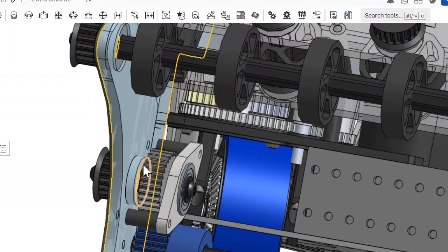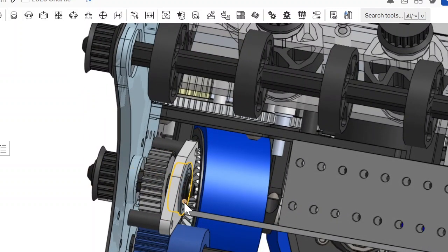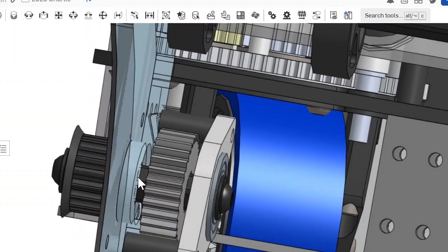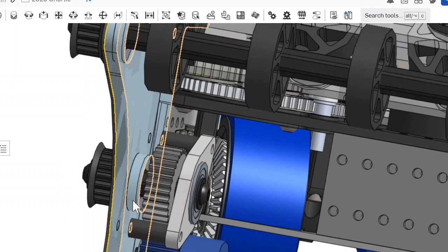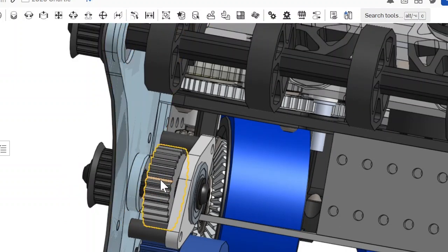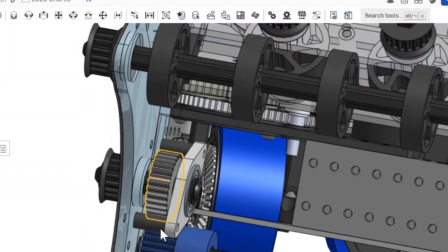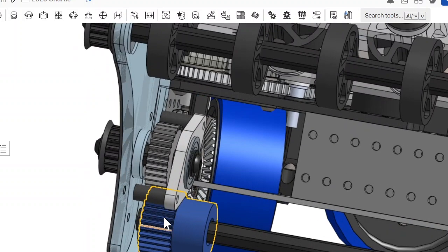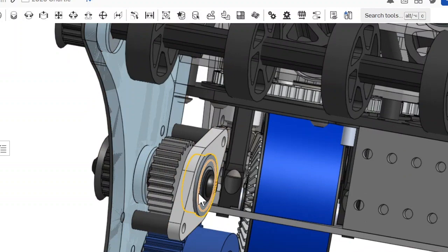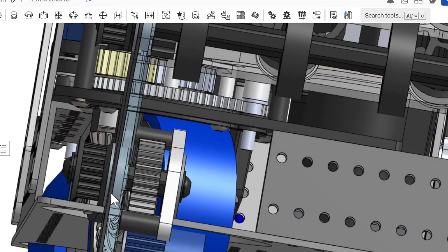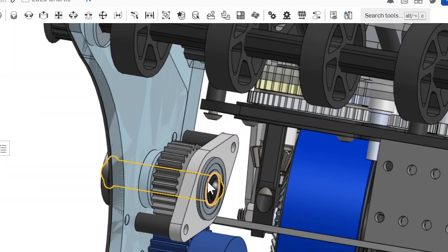And you can see that for that intermediate gear, you do want to have two sides or two bearings to help that gear rotate. If this wasn't here, this would be cantilevered around the center. It would technically work, but it would be rather weak. This thing would bobble around a bit. It wouldn't be fully supported, and that would make the meshing of the gear inconsistent, as well as the tension of this pulley. So you really want to have your shafts constrained at a couple of points to make sure that shaft is rotating true as it's spinning.